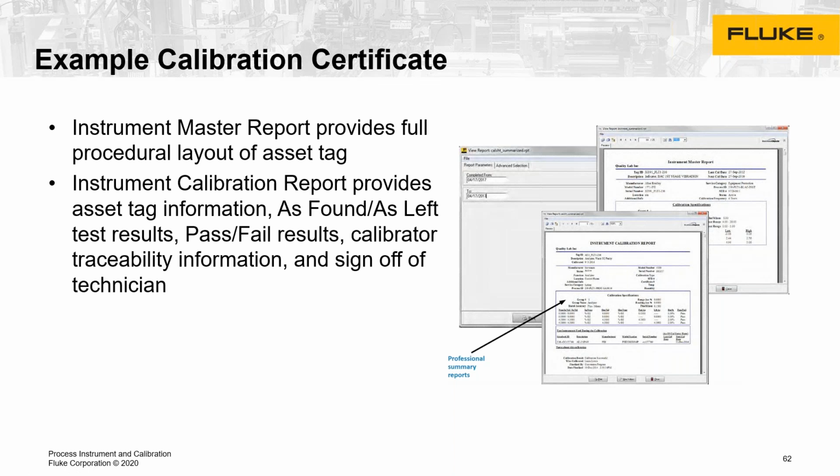And because you've entered when the last time it was calibrated, either by yourself, if you have the capability, or a third-party lab, or Fluke's factory, which can recalibrate these instruments, it's actually going to put that information into the document. So you have full traceability through the actual Fluke calibrator that you used. If the information about the test instrument passed with the asset does not match something in the database, it provides a notation that the calibrator used in this calibration was not logged in the database, therefore they don't have any information about its calibration traceability.